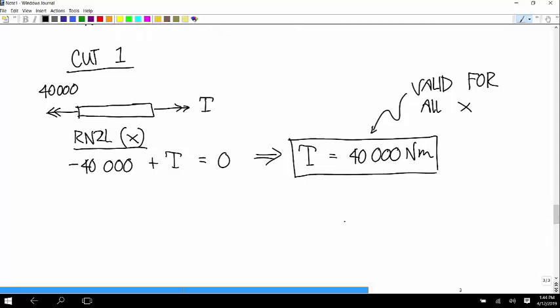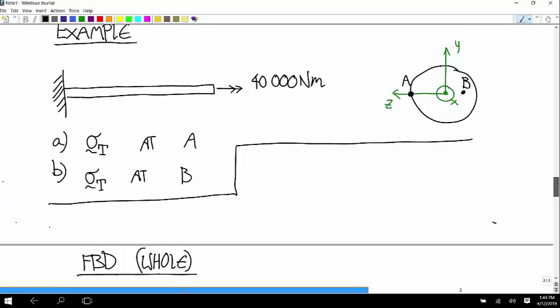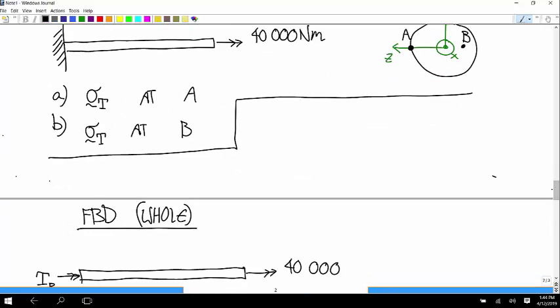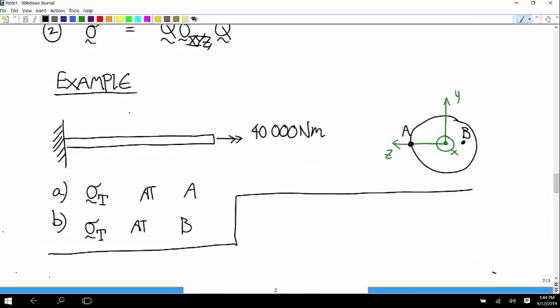And now that we know that, we can calculate the polar moment of inertia. That's pi over 2 times r to the fourth. Did I give a radius for this? 0.05 meters, 5 centimeters. So the cross-sectional radius is 0.05 meters.